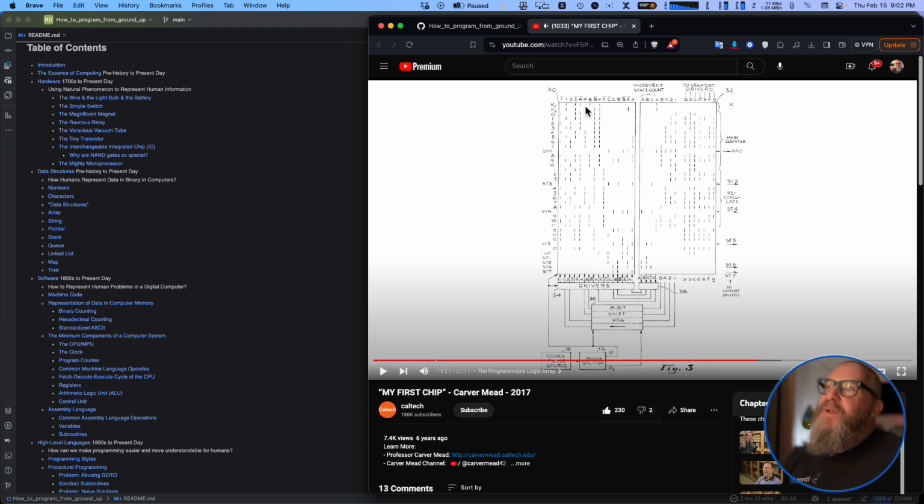So what this is showing here is where all the wires are connected together. Yeah, it looks like that's what he's doing there. And this is the program for his field programmable gate array. So all the places where it's got a line, it's going to remain connected. And everywhere there's a gap, they've blown the fuse, as they say, for that connection.